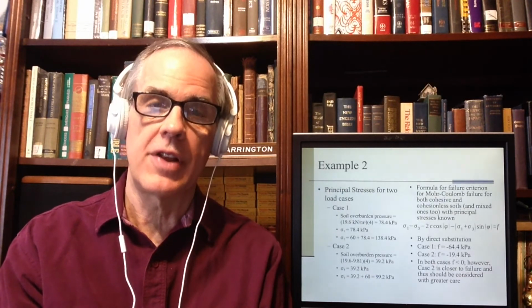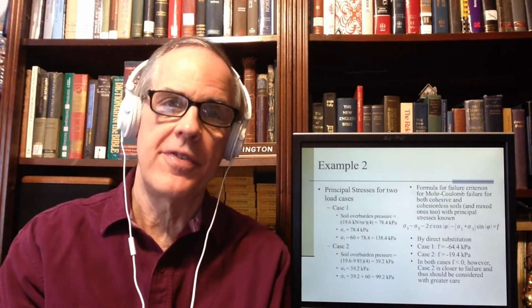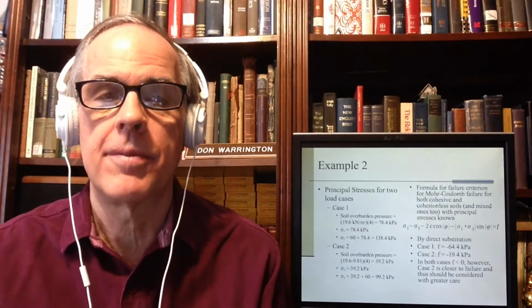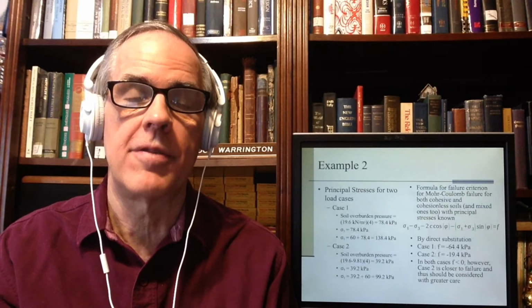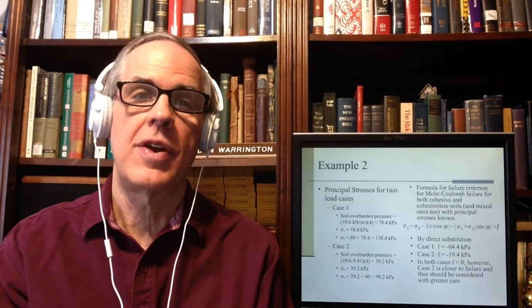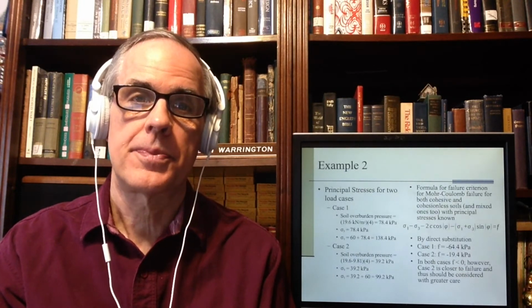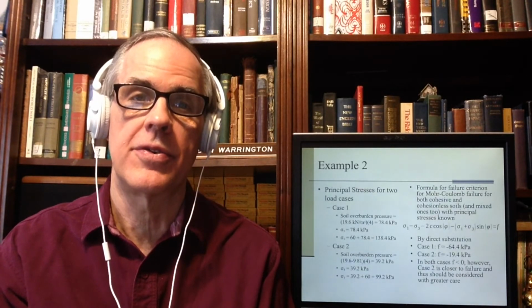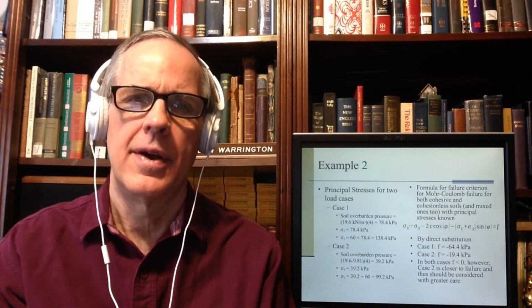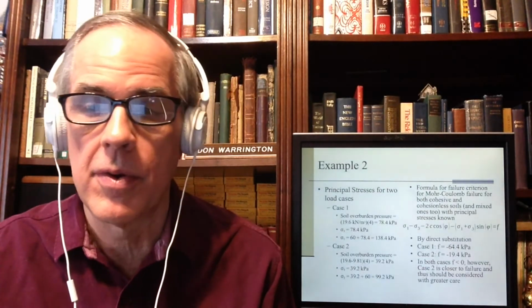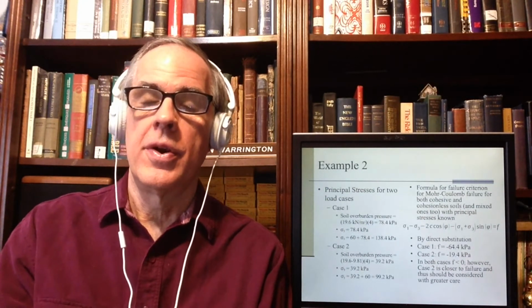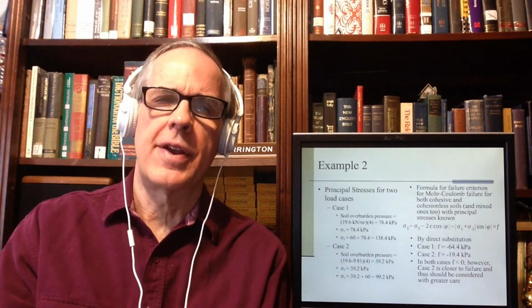But the second case is closer, and that shows you the general effect of raising the water level in the ground: it decreases the effective stress, and by doing so, it decreases the soil strength, particularly in cohesionless soils. Cohesionless soils are a little different, obviously, by Mohr-Coulomb theory and in practice. So the second one should be given greater care because obviously I'm approaching the failure envelope.